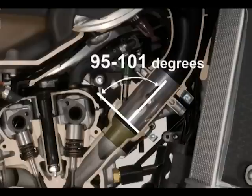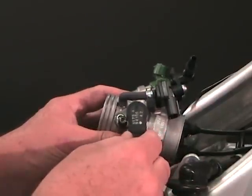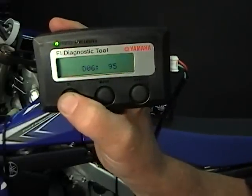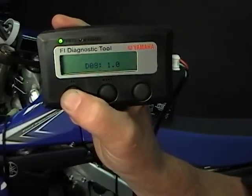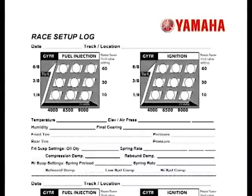The Power Tuner will show 0 when the throttle valve is closed, so if the TPS is removed or the setting changed, see your dealer to have the TPS properly adjusted if you don't have the optional FI diagnostic tool and sub-lead assembly. Your dealer can get you copies of this sample race setting log sheet to help keep track of engine mapping and other engine and chassis settings.